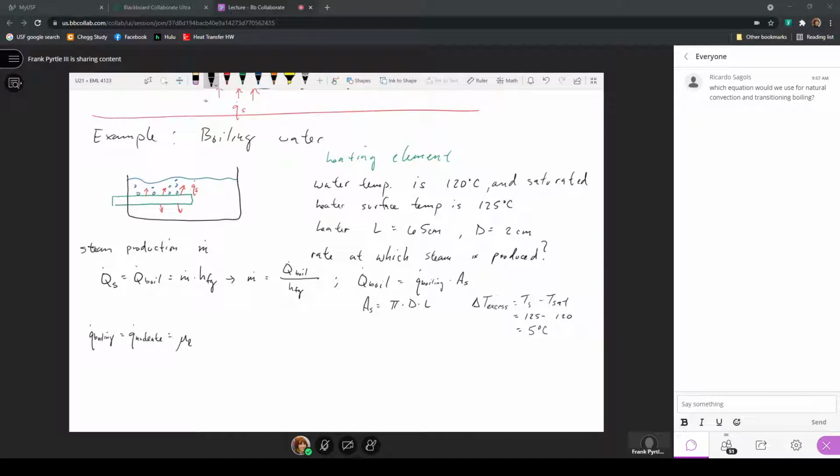This is the dynamic viscosity of the liquid phase times the latent heat of vaporization at 120 degrees times the gravity of 9.81 meters per second squared times the density difference between the liquid and the vapor divided by the surface tension, all this raised to the 1/2 power, times the specific heat of the liquid phase times Ts minus Tsat, which is just the excess temperature, divided by this constant C sub SF for nucleate pool boiling times the latent heat times the Prandtl number of the liquid phase raised to the N, and this entire quantity cubed.